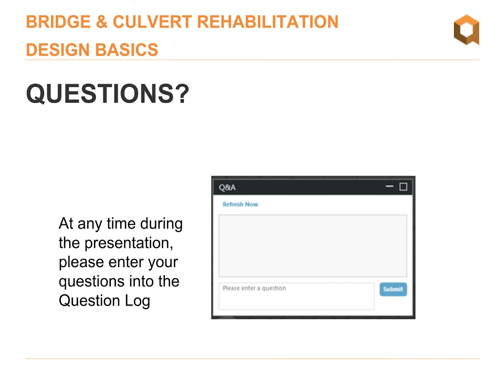Normally, when we grout these structures, the structure is completely dewatered, and during the installation of the grout, there would be no water flowing through the structure. And of course, water would not be diverted back through the structure until all grout has completely set. So realistically, in a typical situation, there wouldn't be the opportunity for grout to actually drip or seep into the flowing stream. But yeah, we can certainly dive into that one a little bit more to see, just in case, what the impact would be, for sure.